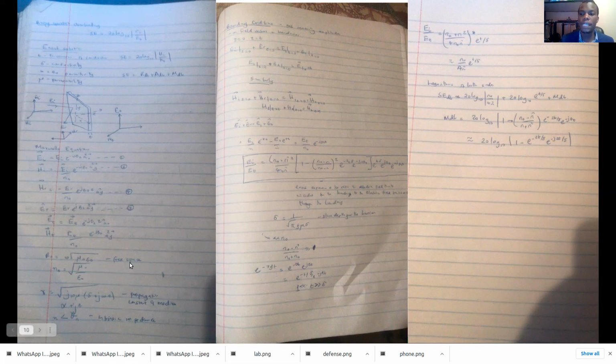Those are the permittivity and the permeability of the material. Then the propagation constant is gotten by the formula. The propagation constant, not beta but alpha, is a complex variable which has both the real part and the imaginary part. So the real part is alpha. When you resolve this equation, it is alpha plus j beta.